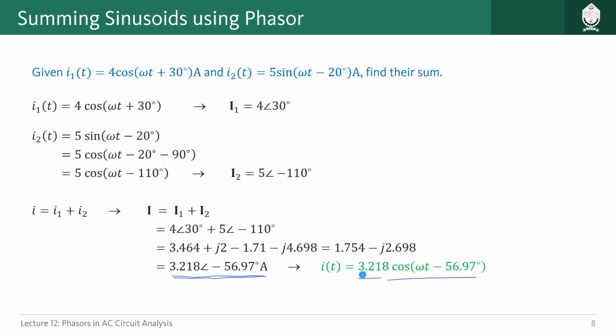So we have taken the amplitude here, this one, cos, obviously it should be a cos signal, omega t minus this phase value, right? In this way. So very simple to understand, but you see the whole addition process or summing process has become much simpler because of taking the phasor. Previously, if we had two cos signals like this or two sinusoids like this, adding them would use different formulas, right? But here we have simply calculated that using the phasors. So this is the second benefit we discussed earlier of phasors.